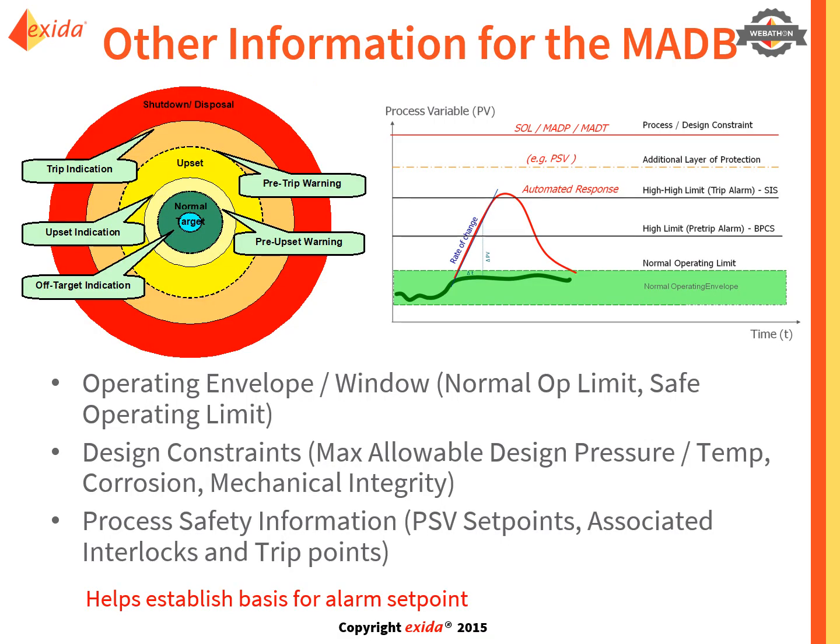Now there's some other information you may want to include. You can have a master alarm database to do with the normal operating envelope of the plant and how your alarms relate to that. Now SILAlarm will function without them, but this information can be useful when deciding whether to add or delete alarms, and trip points are a good example. You may want a high alarm well before you trip, but you may want to also know that you've actually tripped. If there's no action for the operator, the consequence has happened after all, that could be considered an alert, so not an alarm.